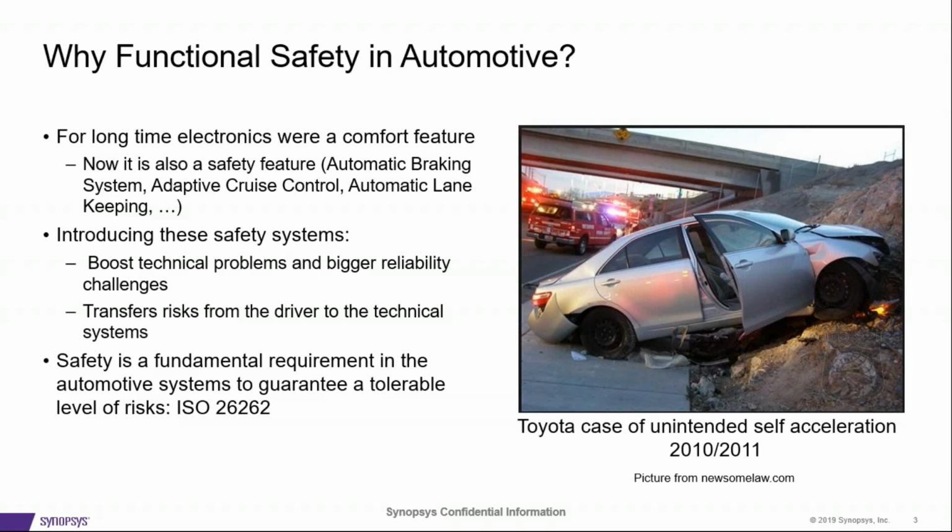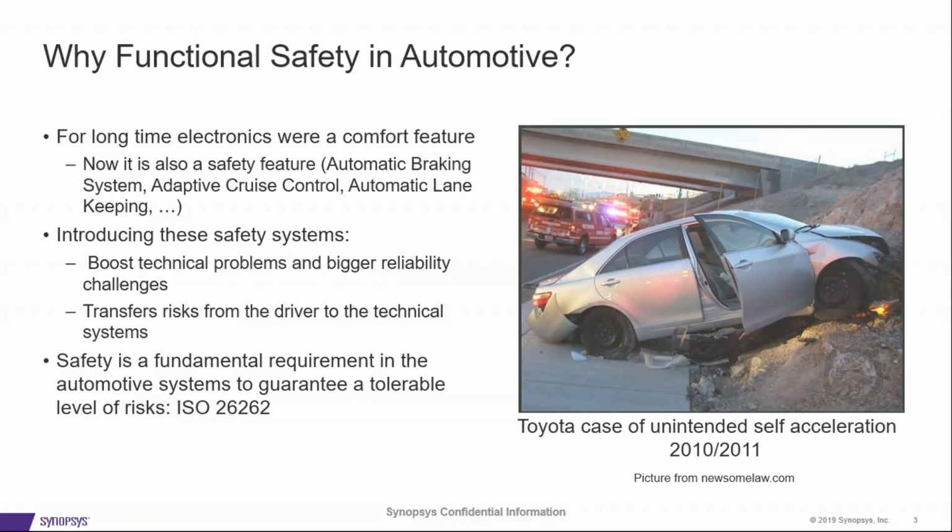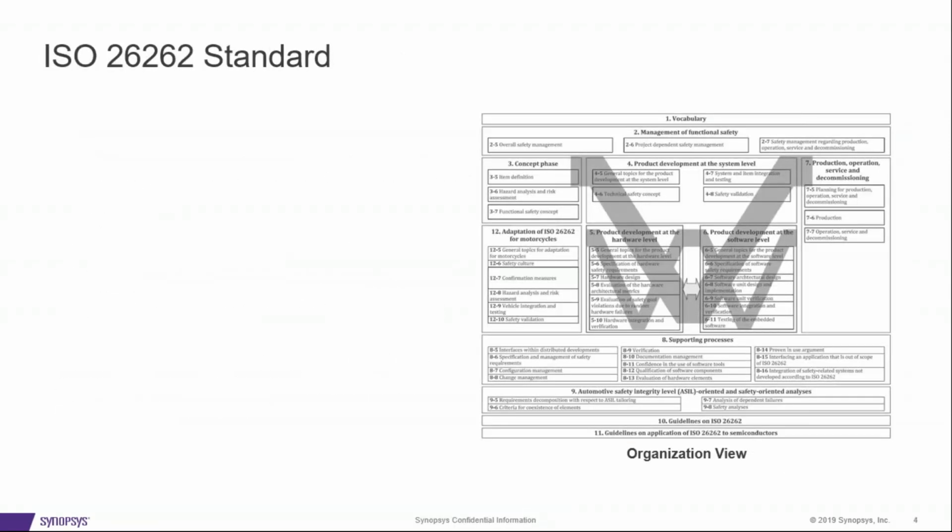It's the part that deals with hardware, and essentially it describes the requirements and general guidelines for designing an automotive system from concepts to the vehicle itself, vertically as well, from the vehicle level to the overall system down to the IP level, in which most of you are probably involved. So designing RTL, doing verification for IP that is going to go into an SoC, that's going to go into a tier 1 product that's eventually going to go into an OEM.